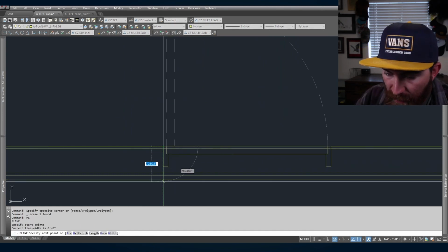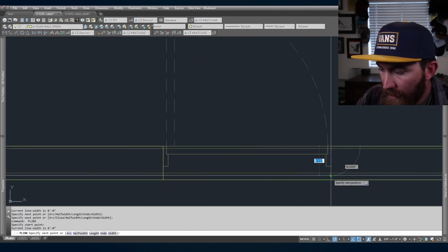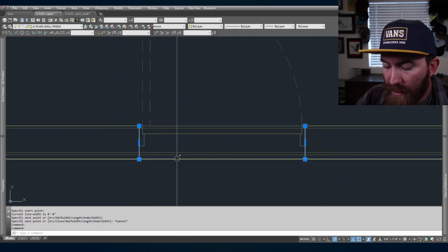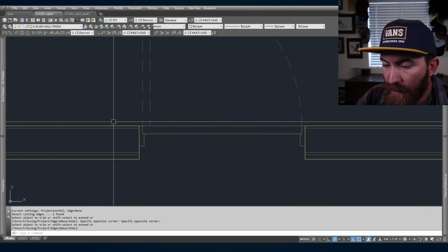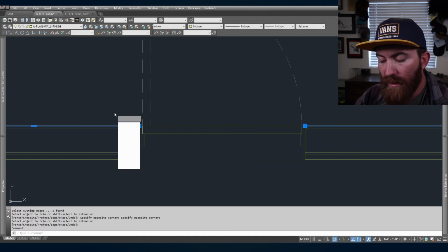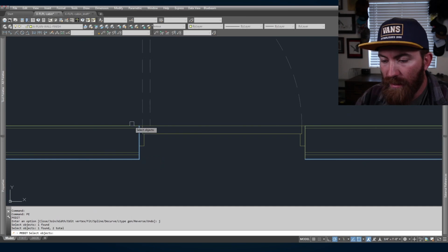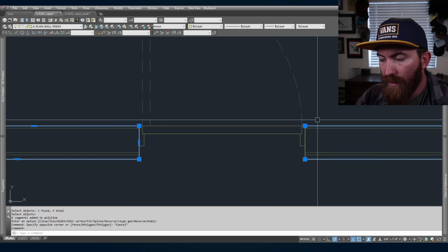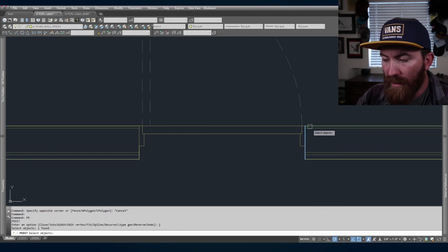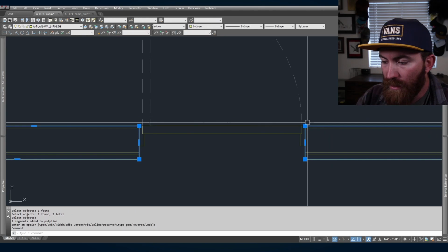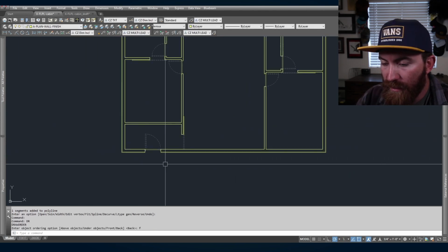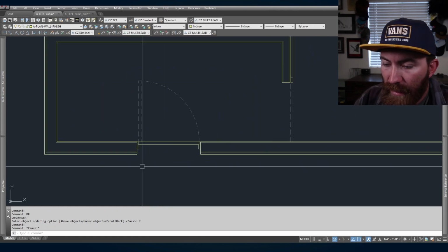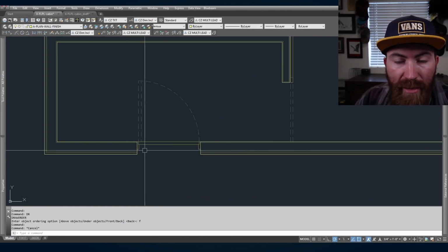Go here, we're gonna hit polyline, hit polyline right there. And we're gonna go ahead and just select those and trim everything in between. Boom. Now we're gonna do poly edit, join this and this. Poly edit, join this, I forgot to select that. Now it's all draw order front. Now it's all one big polyline. Okay, there's that. And now we're gonna start drawing blocks for our windows.